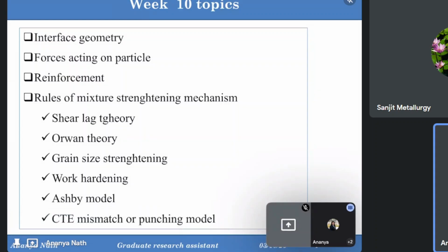They will have their separate properties and try to maintain them, due to which there is a significant advantage of using metal matrix composite over alloy: we can achieve the properties of the parent metal and the properties of the reinforced material separately. But in case of alloy, we get mixed up properties.